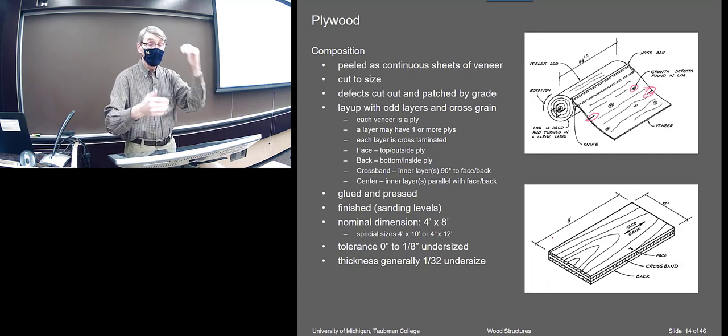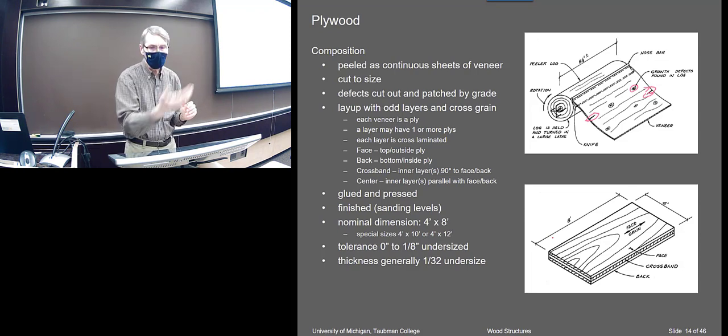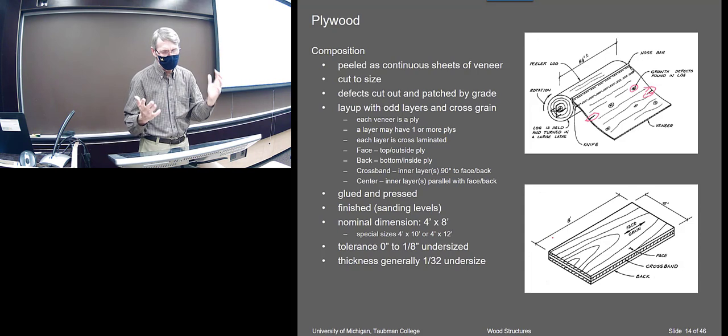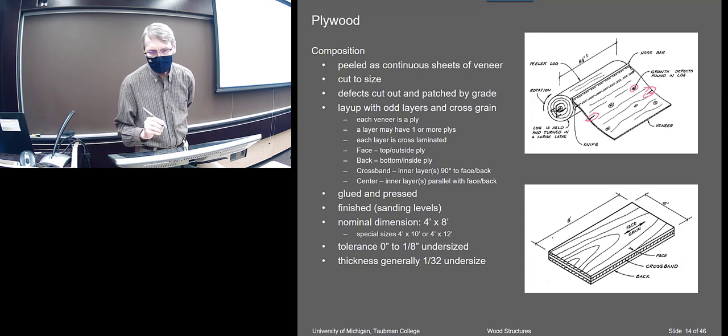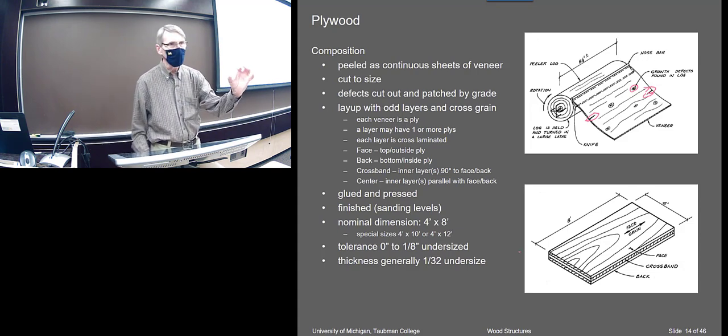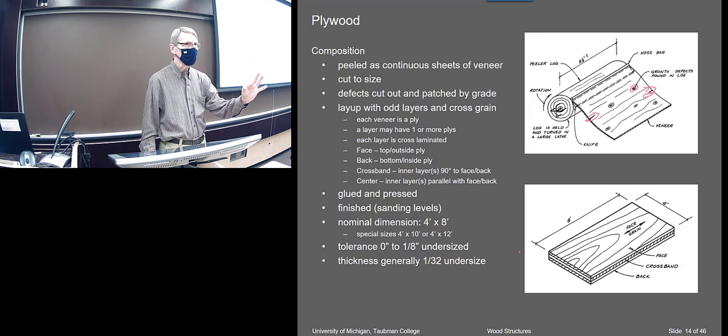I suppose it probably is. They scan it, and that detects the knot holes, and there's an algorithm that grades it. There probably is for this too. Maybe that video is a little bit older. I don't know. But some of these knot holes can be repaired. Some of them, if they're small enough, I mean, you've seen plywood. They don't necessarily fall off. You just have the knot hole in the plywood, right? So that stays in there. I think below an inch or something, you can imagine. And bigger ones, of course, they can either cut them out.